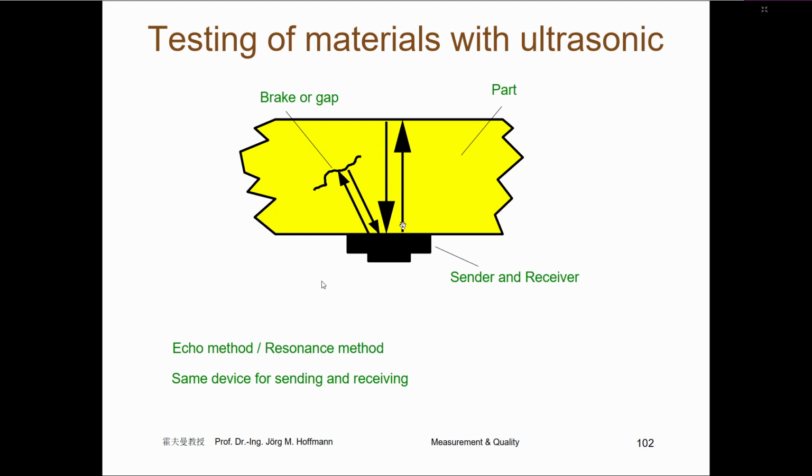And when you get a phase shift between the sending signal and the response signal, you can look at how big the phase shift is, and so you can also use the piezoelectric sensors to measure the distance.